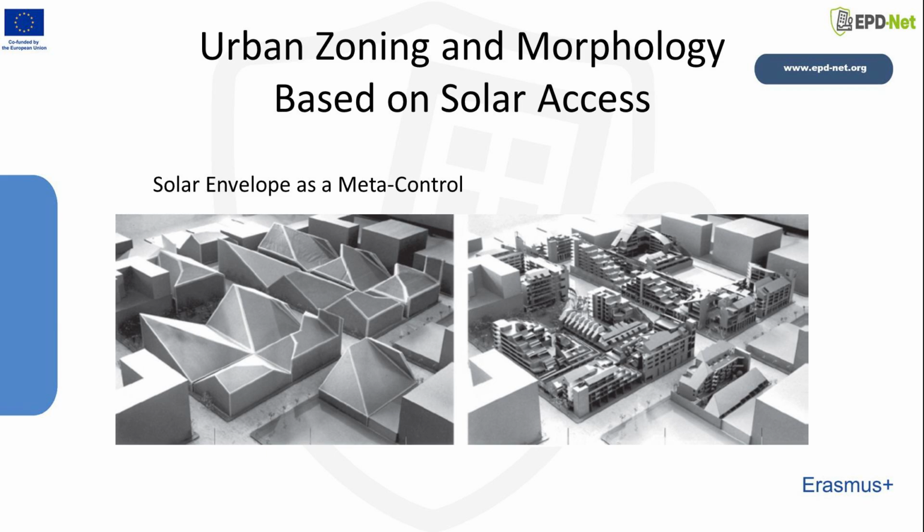When applied, the solar envelope forces building form to respond to orientation. Development tends to be lower on the south side of a street than on the north, preserving the major southern exposure. Buildings and streets gain distinct directional identities. Because the envelope is generated by the sloping rays of the sun, the resulting forms are complex, multifaceted crystals or warped surfaces, leading to unique shapes rather than repeating rectilinear designs.